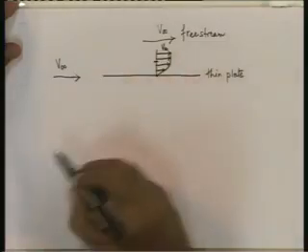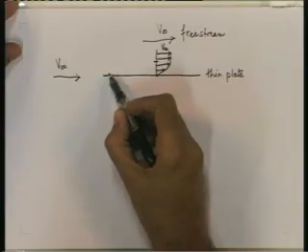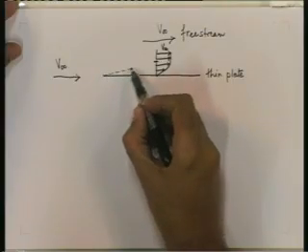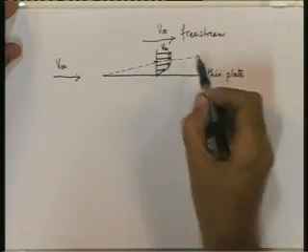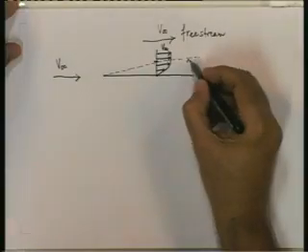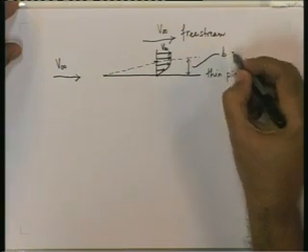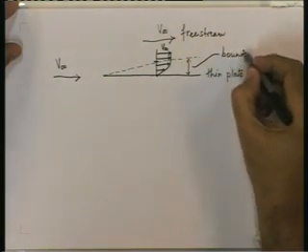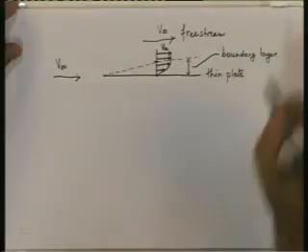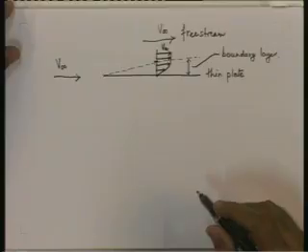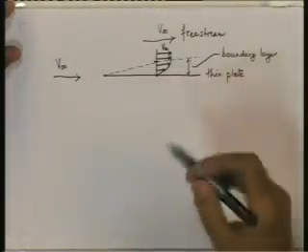Near the leading edge, this effect is much thinner, and as you go away from the leading edge, you find a zone in which the velocity is lower than the free stream velocity, and this layer is known as the boundary layer. On the other side of the thin plate also you will have a symmetric boundary layer.